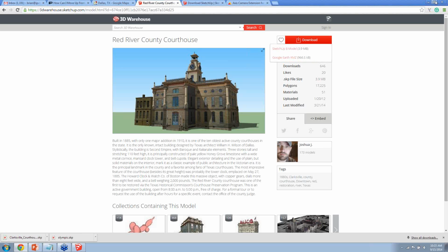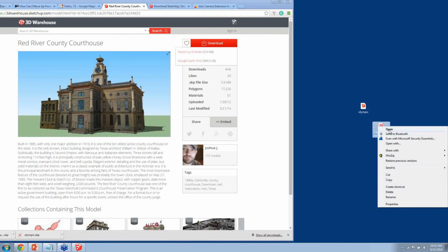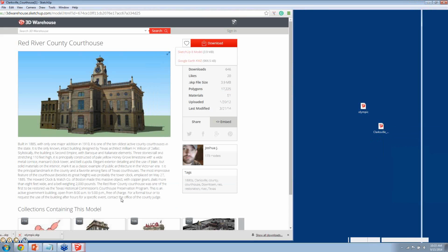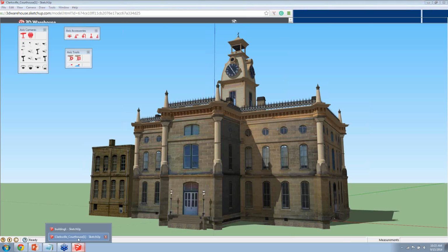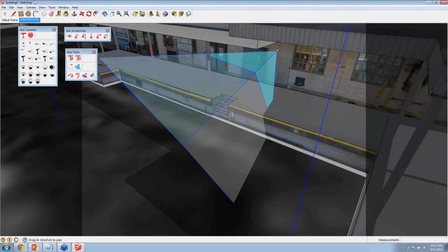But hey, Brian, sorry to jump in here again, but we got a great comment from Ben. He says, once you generally know where your site location is, open up SketchUp, hit the File tab, and scroll down to the geolocation add location. From there, you can search as you would in Google Maps for your site. So, for example, if you wanted to search for a site in Philadelphia, you could type in Philadelphia, PA, start panning around to find what you're looking for, and then you can also enter a specific address if you have that as well. Good comment. Oh, cool. In fact, I'm going to copy and paste that and make that public for everyone to see.